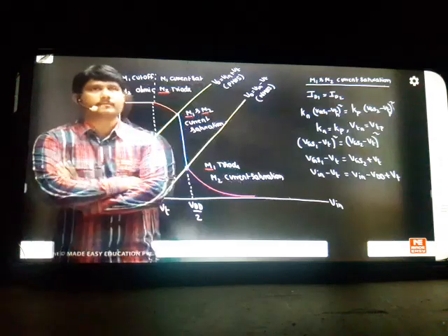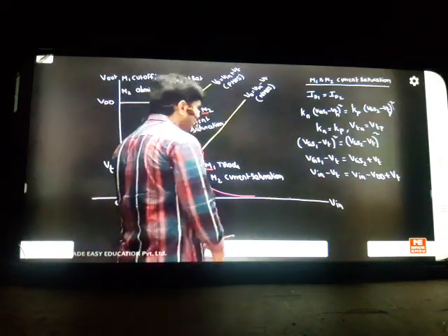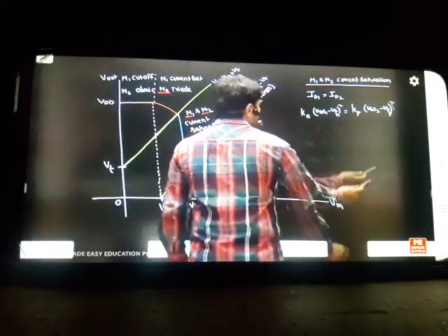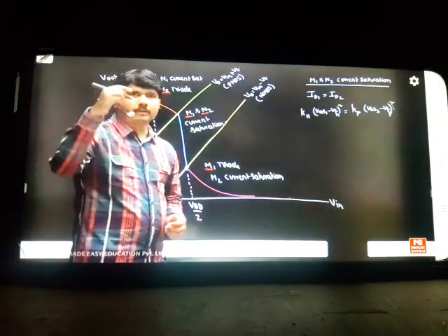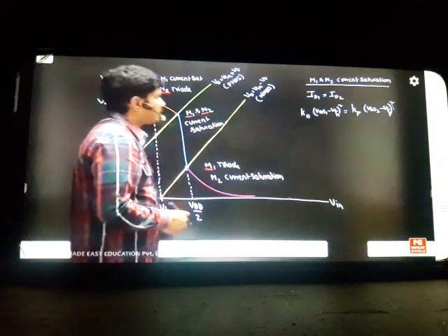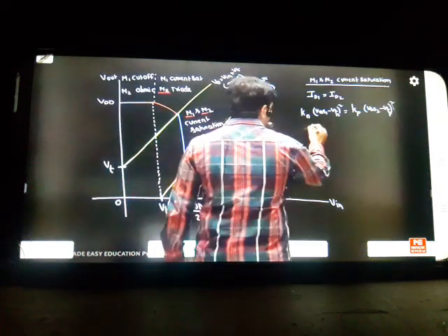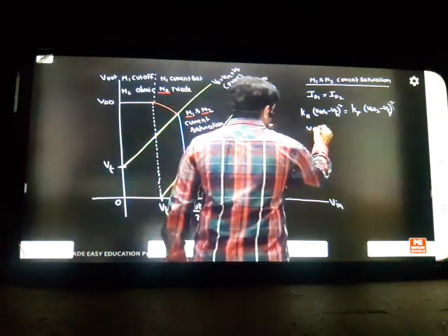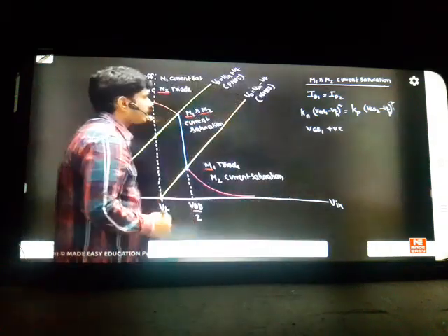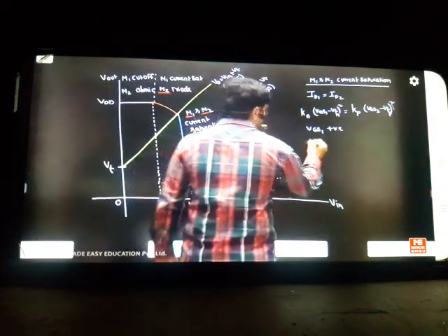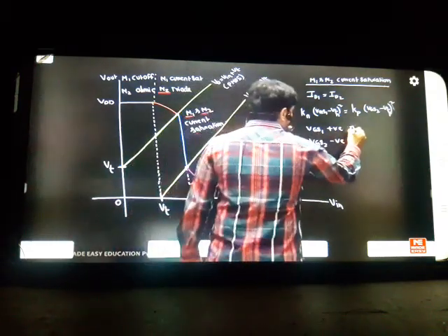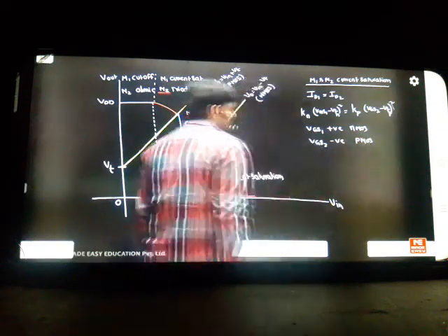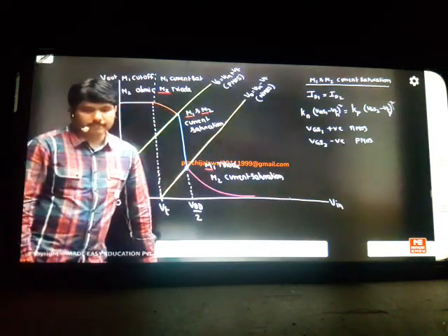Yeah, I think yes, sorry, correct. Somewhere a mistake in the sign technique we have done. Exactly correct, a sign mistake we have done. So what is the mistake I think I've done in the class? We'll see that here VGS1 should be positive for NMOS, correct? VGS1 should be positive for NMOS and VGS2 should be negative in case of PMOS. The sign techniques for NMOS and PMOS are different. Maybe that is the mistake I've done. This is for NMOS, this is for PMOS. That means VGS2 we have to consider as a negative value. Maybe that is the sign difference we are getting.